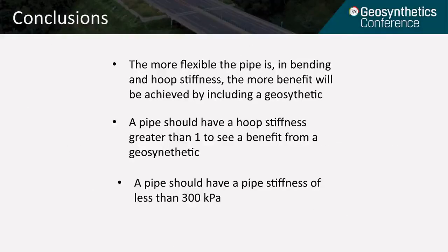Conclusions. Of course, the more flexible the pipe is in bending and hoop stiffness, the more benefit will be achieved by including a geosynthetic. A pipe should have a hoop stiffness factor greater than 1 to see benefit from geosynthetic, and a pipe should have a bending pipe stiffness of less than 300 kPa.